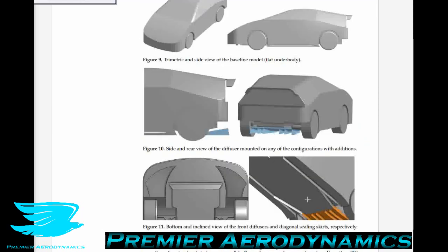The idea of the skirt is that it extends almost completely to the bottom of the car, so like to the ground. The reason we want that is because the more it can extend to the ground, the more it segregates the flow under the body from the rest of the flow around the car. The higher the skirts are from the ground, the more the flow can come in. So that doesn't really help the Venturi effect. To have the Venturi effect occur, we need to really segregate the flow, so when we expand or contract it, the flow can change pressure accordingly.